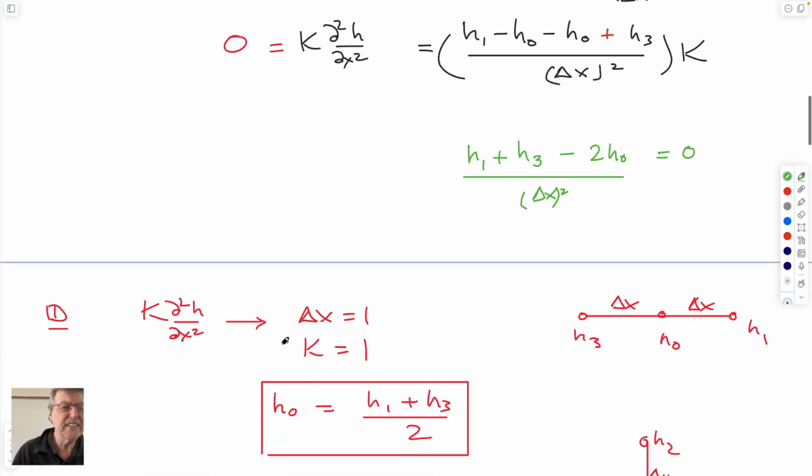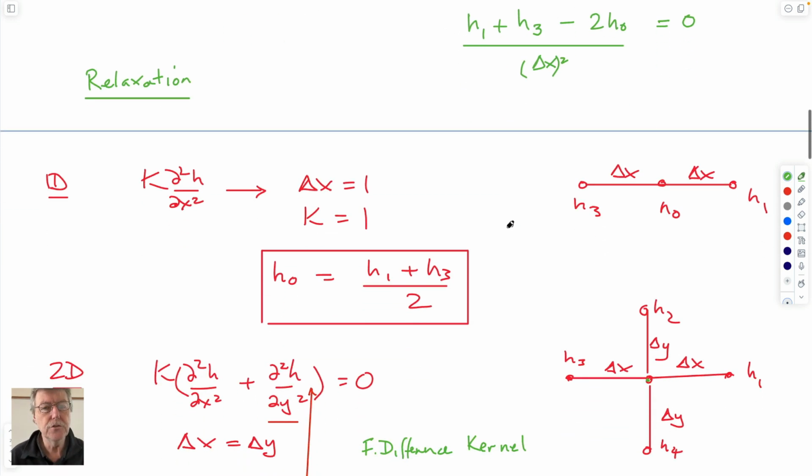The method's called relaxation, or used to be, I think it's still called that, which means that you just work through the mesh to relax the errors until you have no errors, and you actually satisfy this equation at all nodes in your mesh. And then you have the correct solution, which is the same as the solution we had for New Jersey, which would be some elevation of the water table in one-dimensional flows, or a surface for the water table in two-dimensional flows.